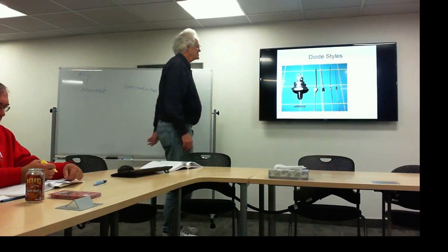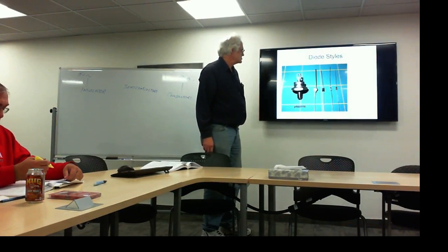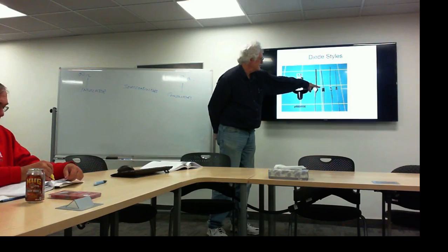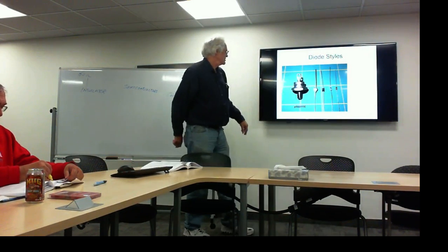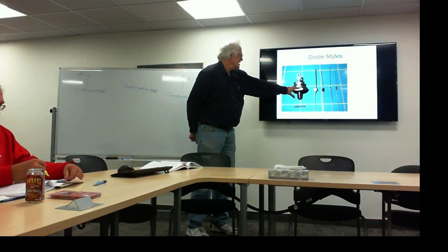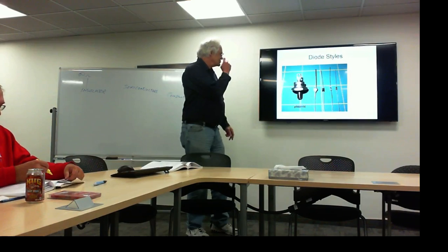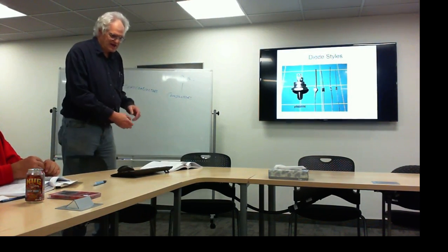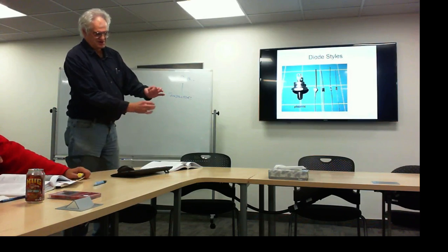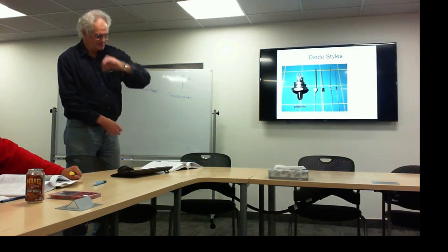And like I said, here's just a few pictures of typical diodes. Typically you see the band on the end being the cathode. Those are some of the shapes and sizes. Obviously, the higher current ones are bigger. Actually, I was going to bring one in tonight. I had a 300 amp one at home somewhere. It's got threads on it about that big.